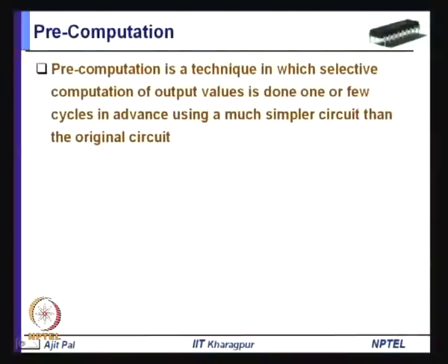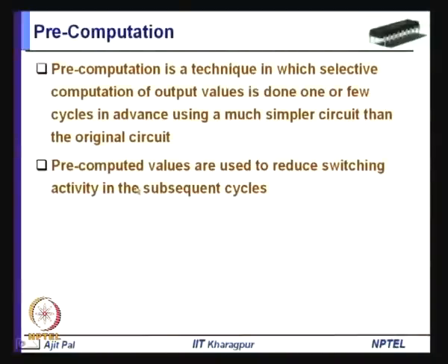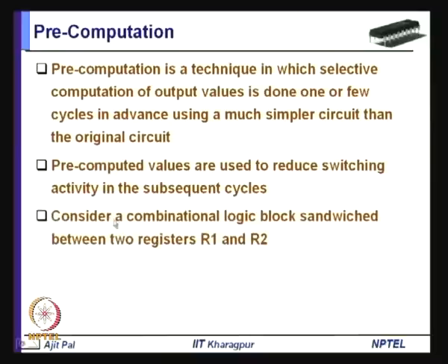So, you will identify some simpler hardware which will do some pre-computation a little in advance, and then you will use these pre-computed values to reduce switching activity in subsequent cycles. That is the basic idea of pre-computation, and pre-computation is done by a simpler circuit, as I have told.